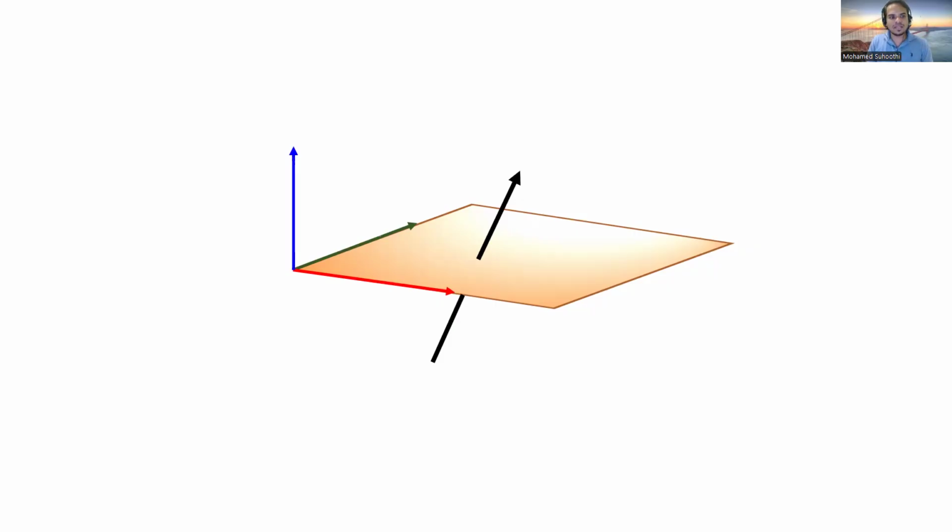Then how can we explain this force? Because this is in an arbitrary direction. So our coordinate system I have represented here. Therefore, I have to decompose this force along my coordinate system. Then, if I decompose the force and divide by the area of this point, the infinitesimal element, then I can get the stress, right?